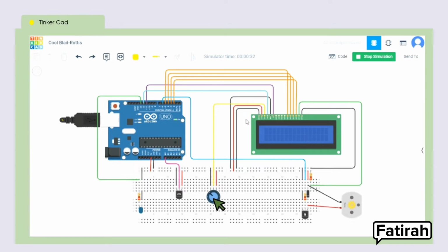Next, the potentiometer. A potentiometer is a simple mechanical device that provides a varying amount of resistance when its shaft is turned. By passing voltage through a potentiometer and into an analog input on our board, it is possible to measure the amount of resistance produced by a potentiometer as an analog value.